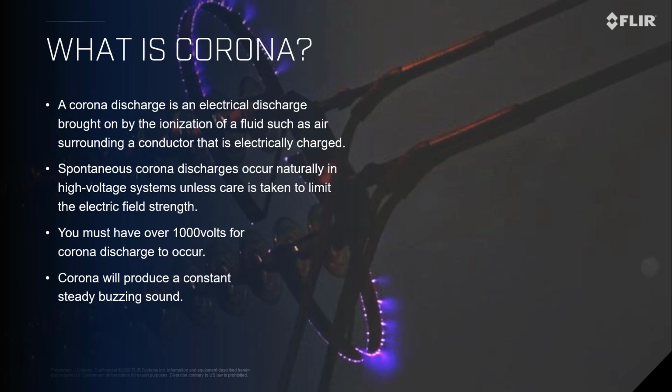Some say it's got to be over 1,000 volts to hear this audibly, but that's not always 100% true, right? We've seen some of these audible buzzing sounds, continuous buzzing sounds, right? Can actually occur in systems as low as 500 volts.